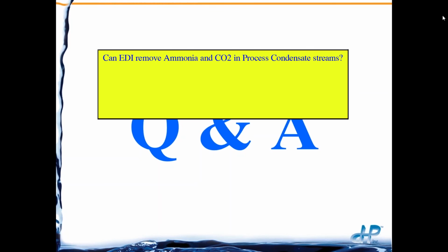Can EDI remove ammonia and CO2 in process condensate streams? Yes, it can, and that's something I've looked at for quite some time. Ammonia can be ionized and removed in EDI applications, as well as CO2. It's definitely dependent upon the concentration of CO2 and ammonia.